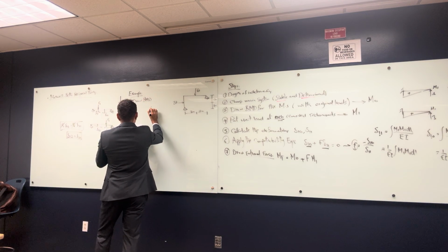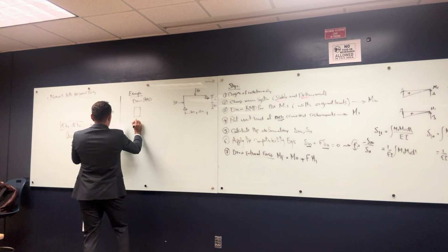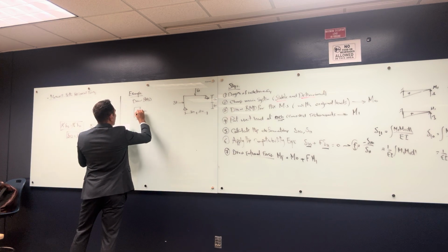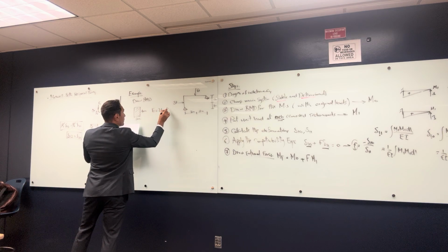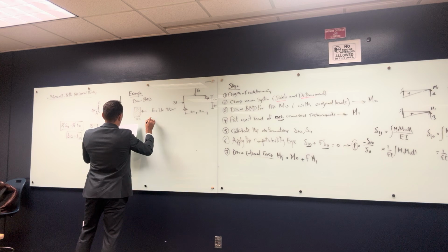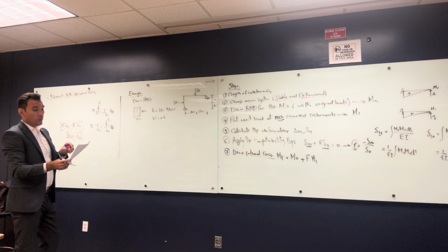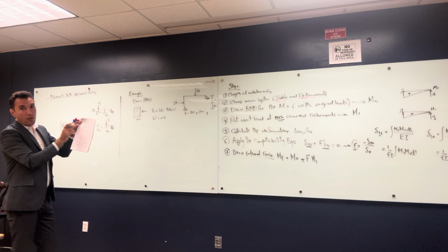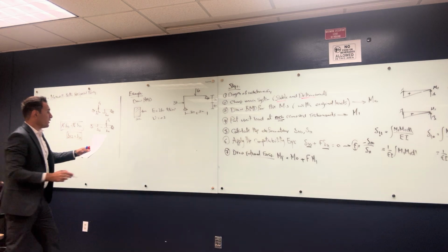For the reinforced concrete frame shown, the cross section is a rectangle, so we are talking about a cross section of the frame of something like 20 centimeter by 40 centimeter. And the E, Young's modulus, is 210 ton per centimeter square. I give you a Poisson ratio of 0.2, but we don't need it, but you will need it here for the example that I have here because I calculated delta that comes from the normal, shear, and moment, but right now I'm only calculating the moment, so I don't need the Poisson ratio. Okay, so let's solve this problem.